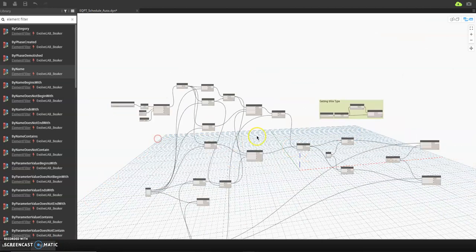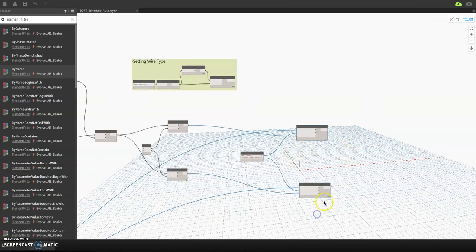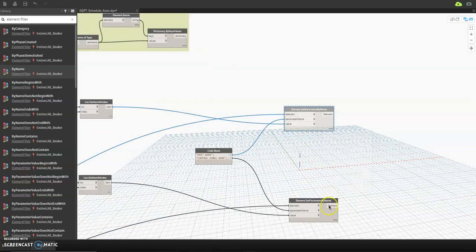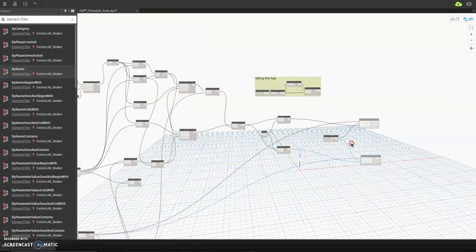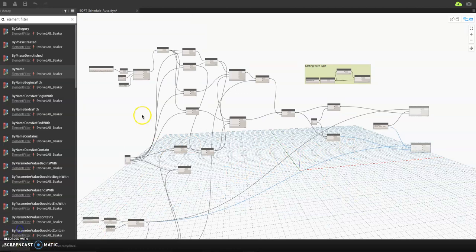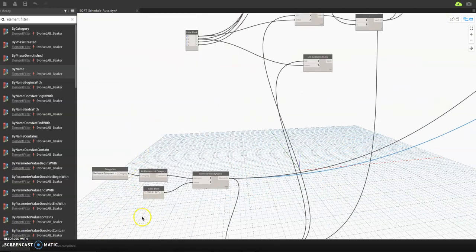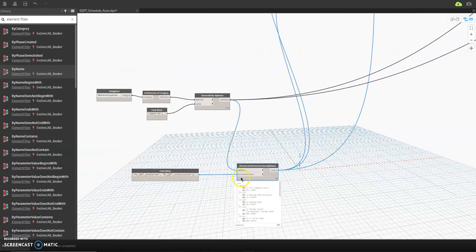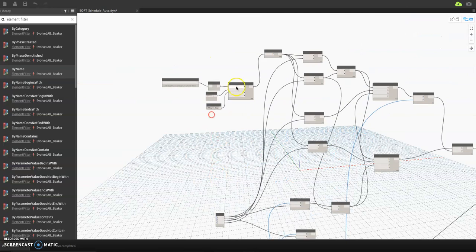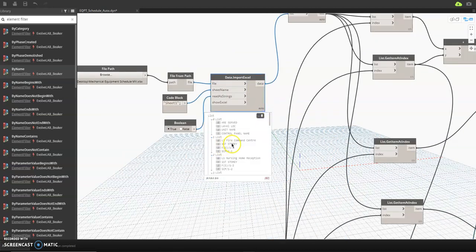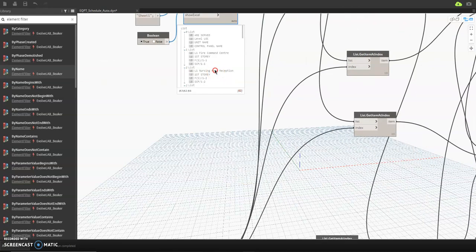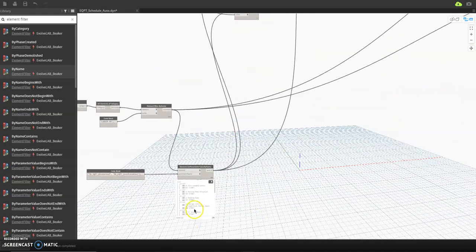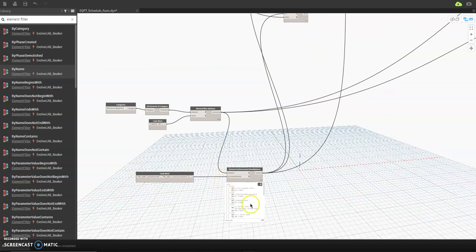I will run this one. I will freeze this one. Okay, freeze, and then run automatic. So if we check now the index, this one. So this is the Revit schedule, and then this is the Excel schedule. So we're going to get the unit name and control panel name from Excel, and then paste it, automated, in the mechanical equipment.